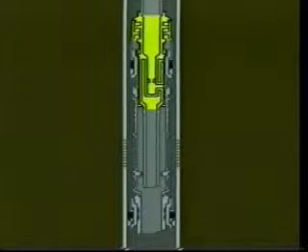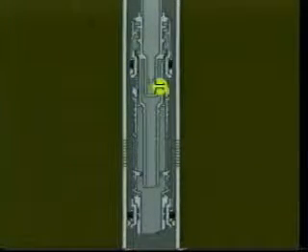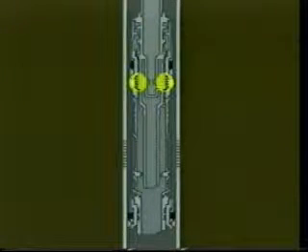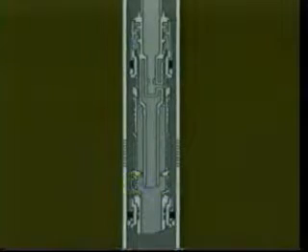The setting tool crossover assembly, attached to the upper end of the packer with a left-hand thread, is sealed off between the packer and the seal bore sub. The gravel pack port is positioned inside the perforated extension, also between the packer and the seal bore sub. The wash pipe extends from below the setting tool crossover assembly to near the bottom of the telltale screen.